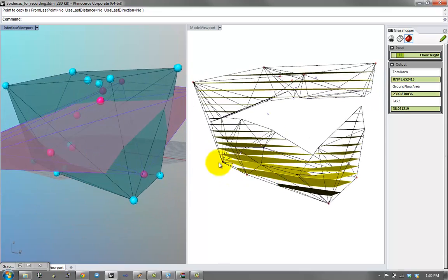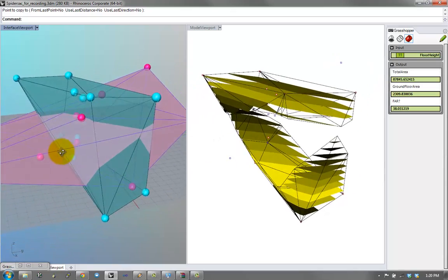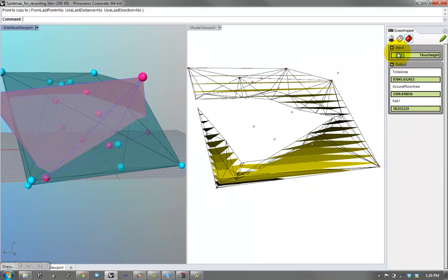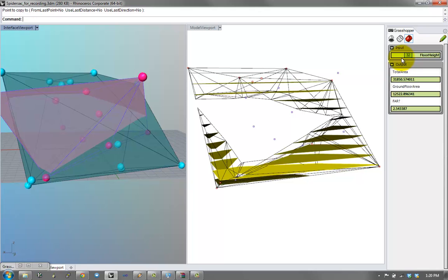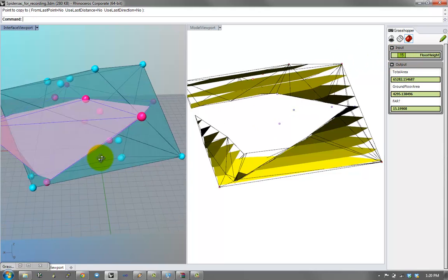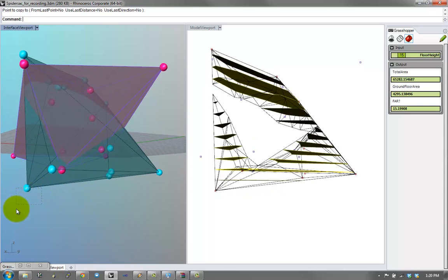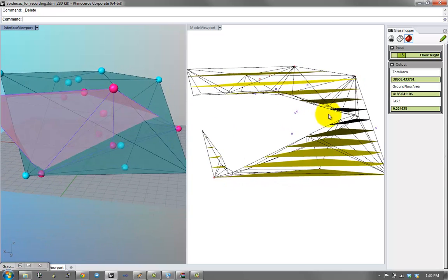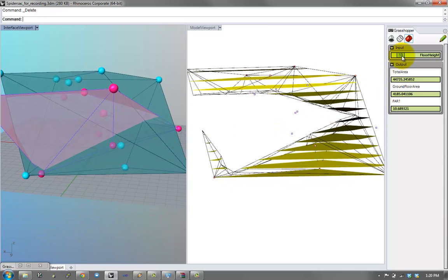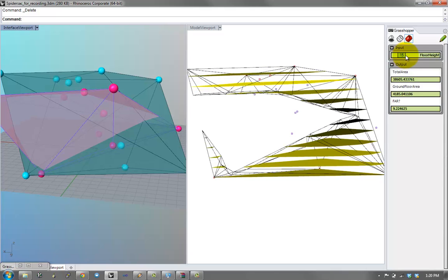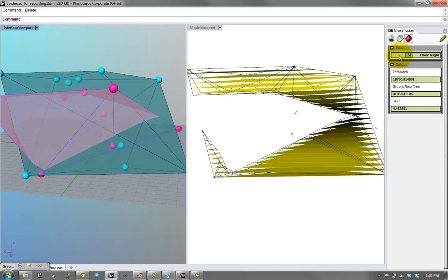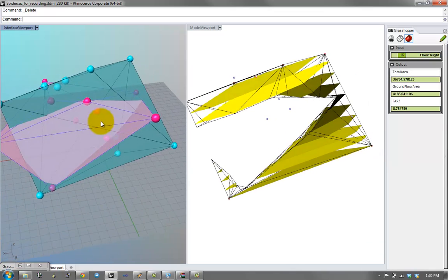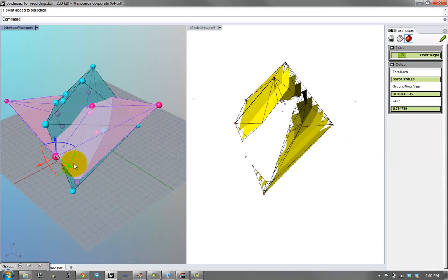I look at a brighter floor and say, okay, that's interesting, but that's not what I want because that floor area is limited. I can monitor my constraints on my right-hand side and say, okay, I'm going to work with my floor height to change the FAR. Let's say it's entirely possible that this is my building and I love this form, but I want to modify the floor heights until the FAR is under 10. So I know that this is what I can get. I could also do this and get certain FARs. So immediately there's this negotiation between the constraints of a project or a task, what I can do, and what I end up with.